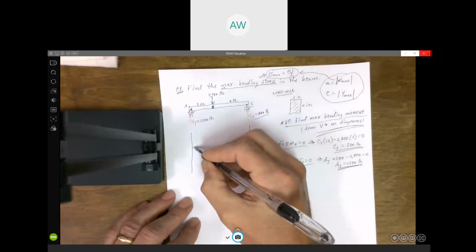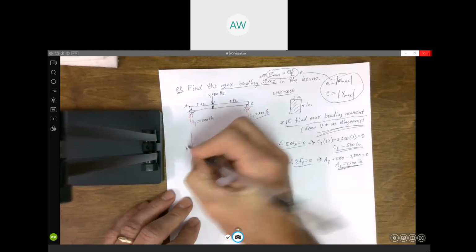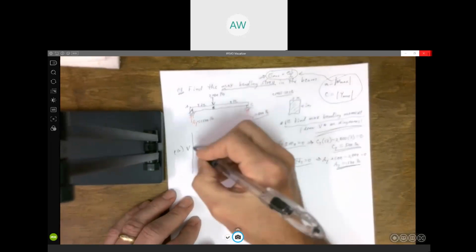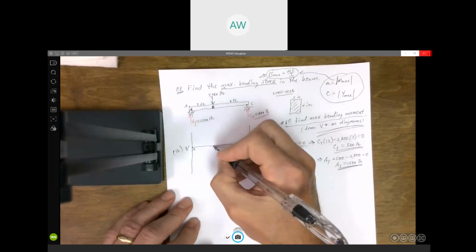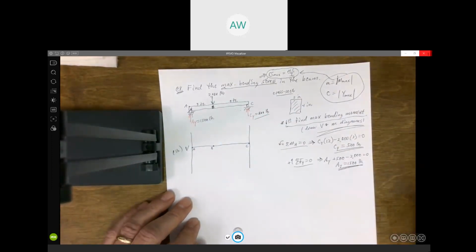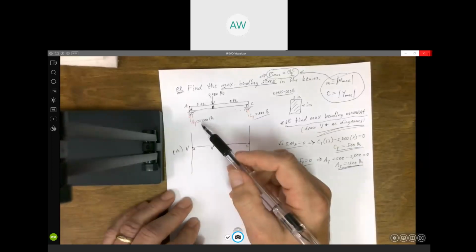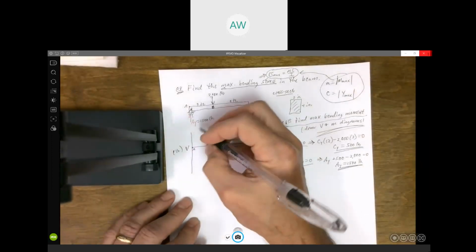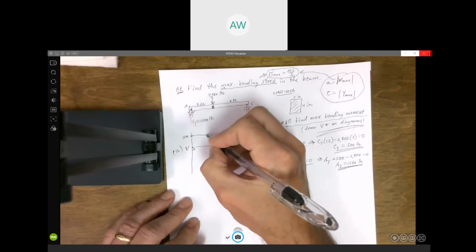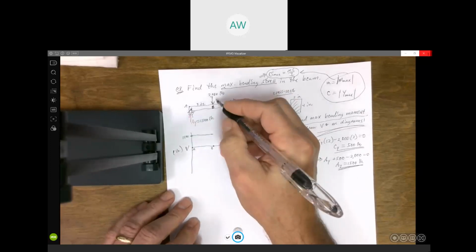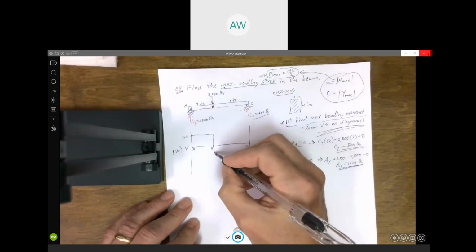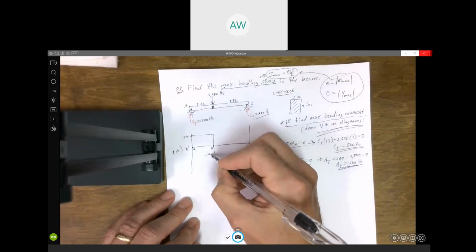So, yeah, this is the shear force. These are in pounds. And we got A, B, and this is C. So I know the shear force is going to be equal to that support reaction. So we're going to start at 1,500. Go straight across, doesn't change till our load changes. And we go straight down 2,000. Puts me at minus 500.